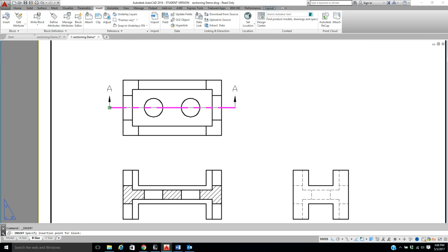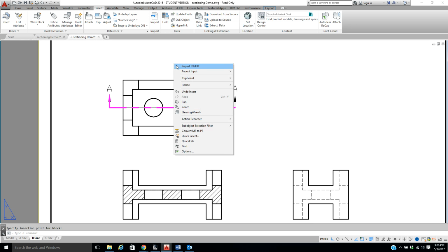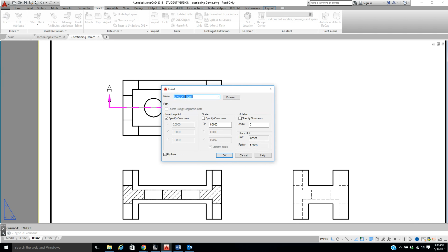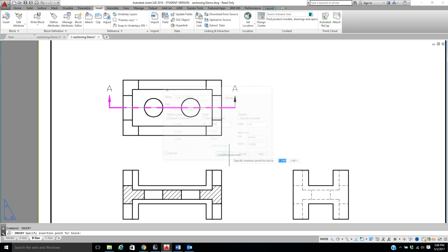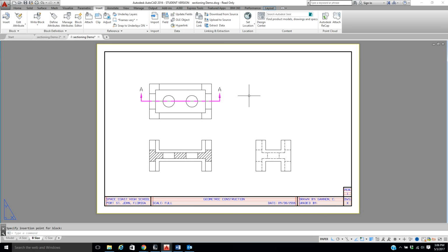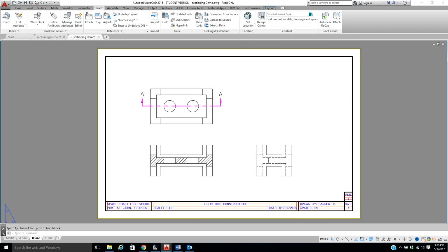And I'd place it right here. Mine came out perfect because -90 means it moved up this way. If I would have done just 90, it would have faced down because mine's coming in. I'm going to right click, reinsert line of sight, and tell it again. Oh, we got to do the -90 again. Another thing I could have done is just copy the other one if I'd liked and go to here. Now that I'm completely all set up. So that is what it's going to look like.